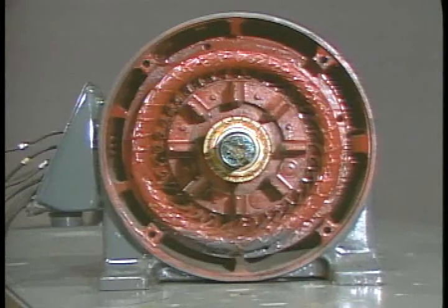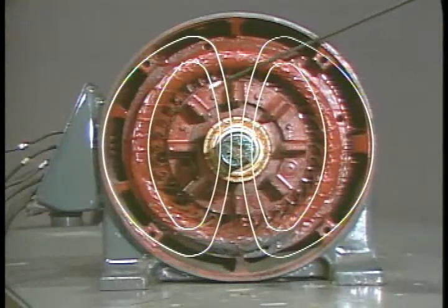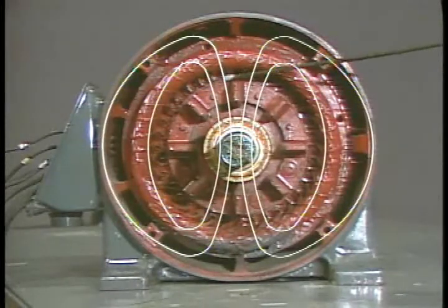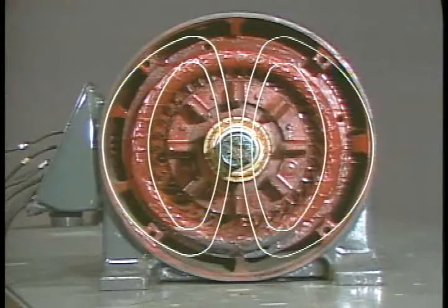Since steel conducts magnetic flux much better than air, and allows stronger magnetic forces to be established, you'll find a lot of steel in a motor. Motors are built so that practically all the flux is carried by steel. Almost the whole frame and housing of the motor become part of the stator's magnetic field. The only place where the flux must cross through air is in the gap between the rotor and stator. This is a major barrier to it, which is why the gap is kept as narrow as possible.